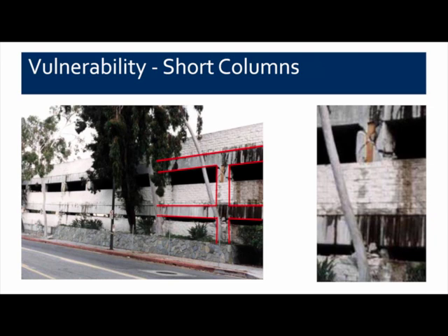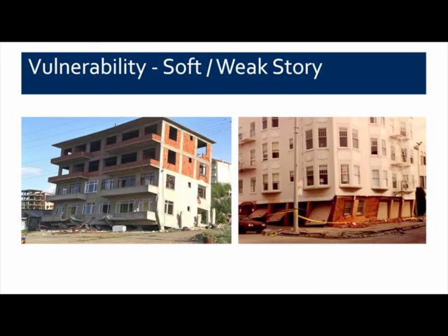And if you look on the right-hand side, a little bit fuzzy, but I think you can see it, the top column that you see there is pretty much completely cracked through and deteriorated. On the bottom there did in fact used to be a column there that has been turned into a pile of rubble, and you can see on the left-hand photo that in fact that second floor has dropped down for a fairly substantial collapse for this building.